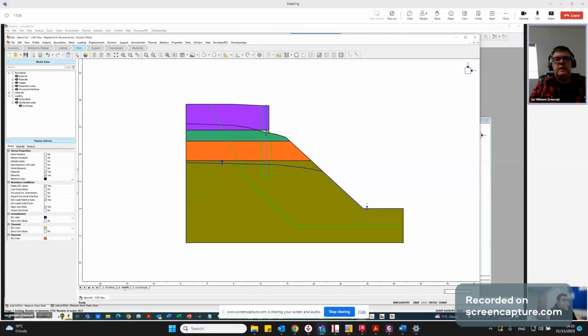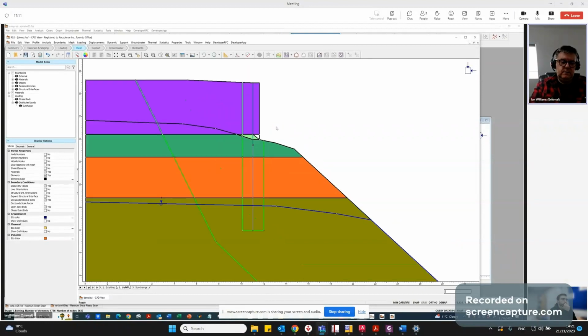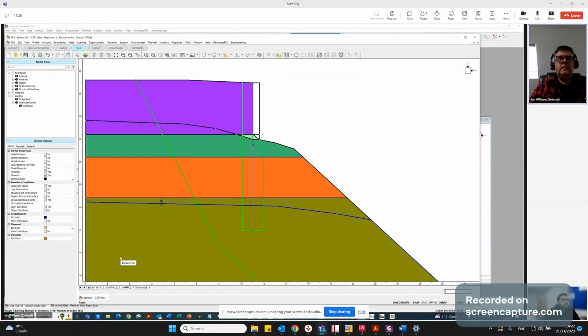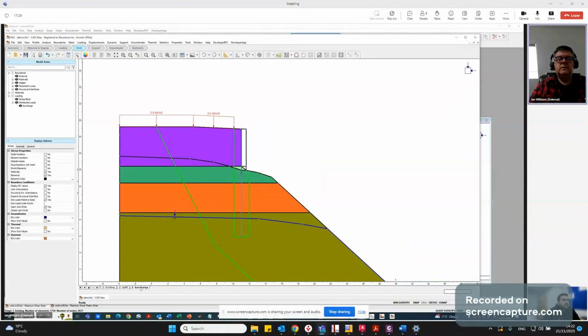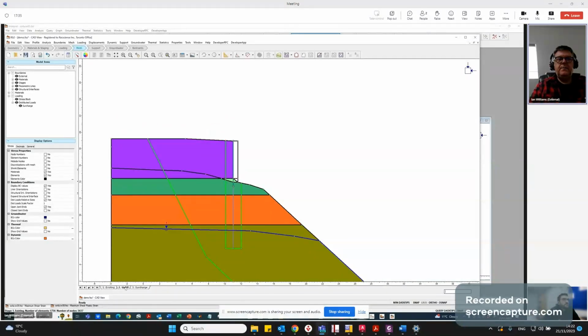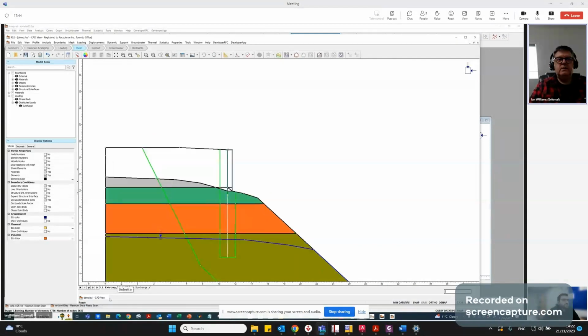So we then upfill, and I just noticed there's a slight error with that, because I just need to excavate that material. And then we apply the surcharge. How do you excavate? When we upfilled, I don't know if you noticed, this fill material, this made ground, has gone from being a made ground material to the 6F2 material.